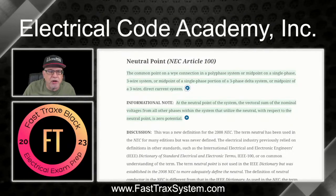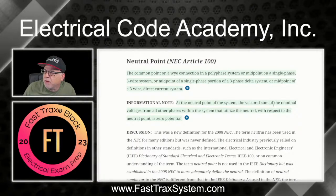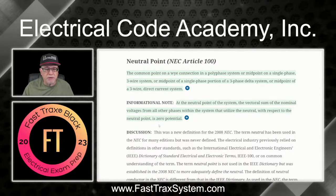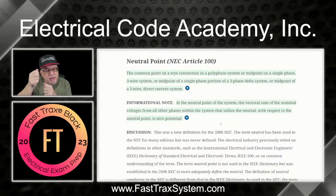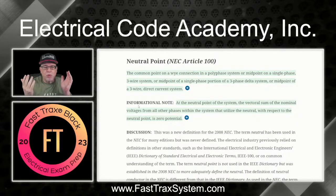Now, this little asterisk right here in our course just reminds you that this is verbatim out of the National Electrical Code. And then, of course, you have an informational note that's saying at the neutral point of a system, the vectorial sum of the nominal voltages from all other phases within the system that utilize the neutral with respect to the neutral point is zero potential, okay? So wherever you're making a connection in our system from the neutral point to all other phases, you're using the neutral point to get that reference, and it's considered the zero connection. That's also how we get stability in reading our voltages. Again, this is an informational note. It's not enforceable, it's just information.